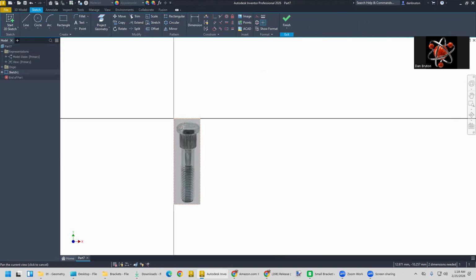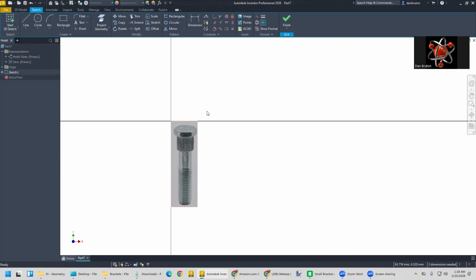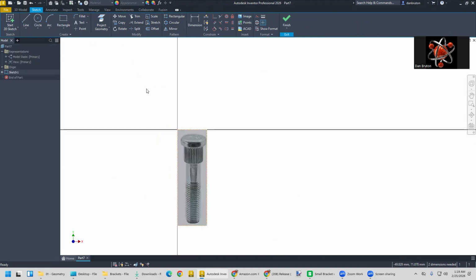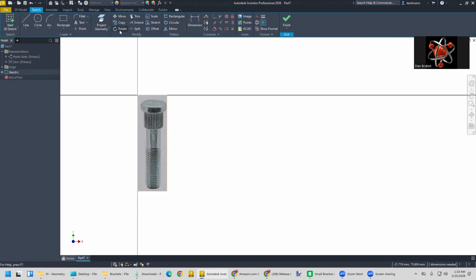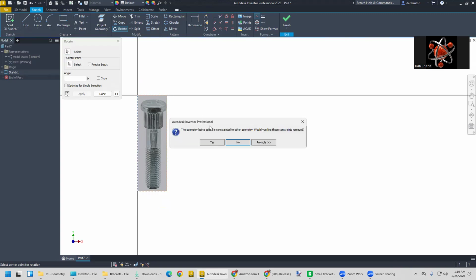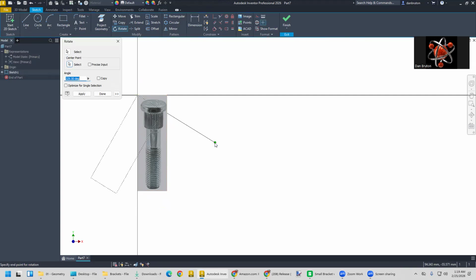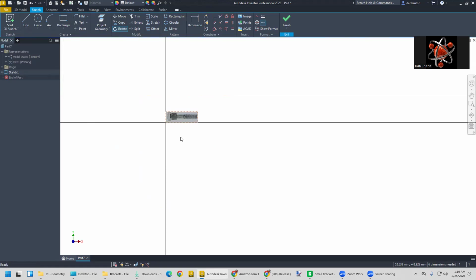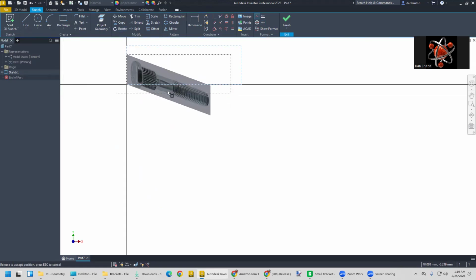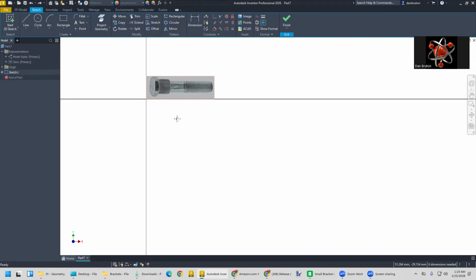And I didn't really anticipate that. Really kind of wanted it horizontal. So what I'm going to do is try to rotate this. I haven't really played around with this very much in these videos, so I'm going to show you how to do that. Go to the rotate tool on Sketch, select a point, and then I think you select, oh wait, the center point here. Oh wait, let's see, there we go. Then you can rotate it around like so. But we prefer to kind of move it over toward the origin a little bit, but that's okay.